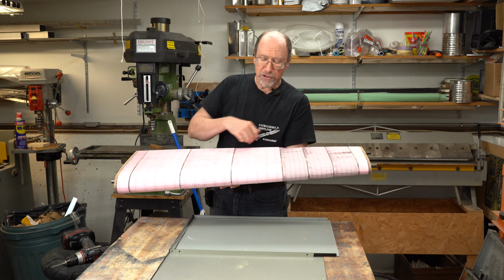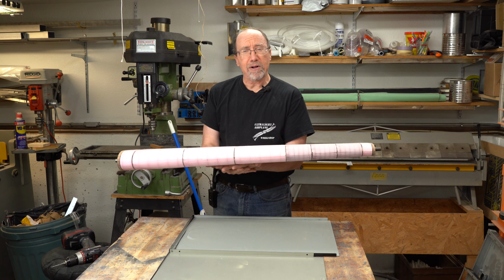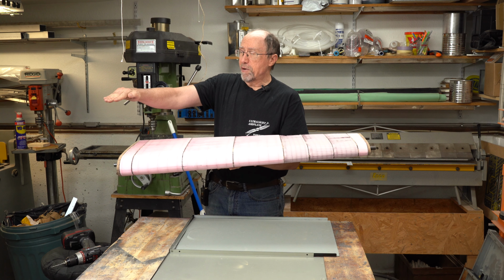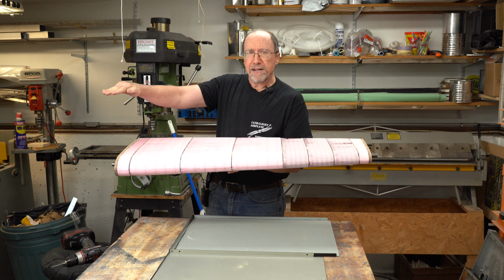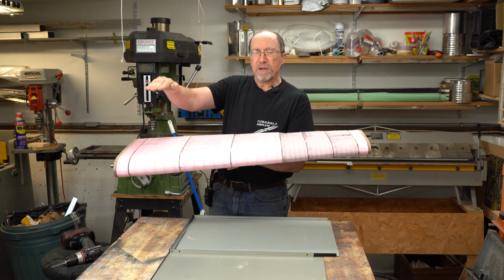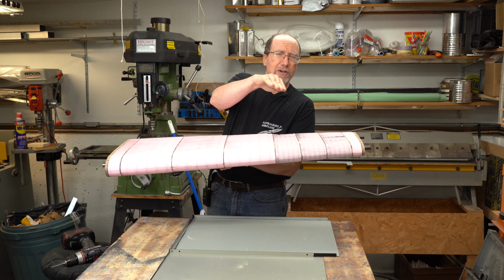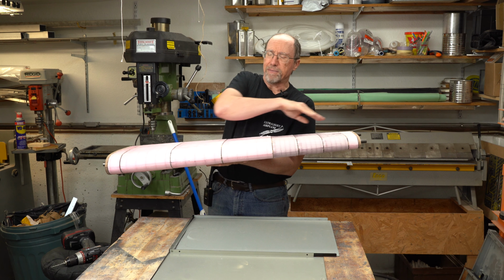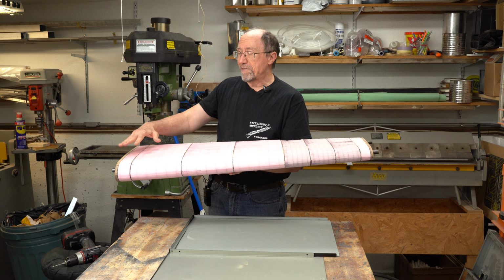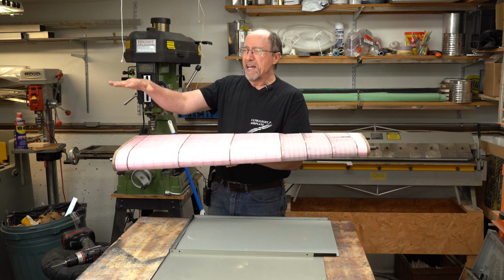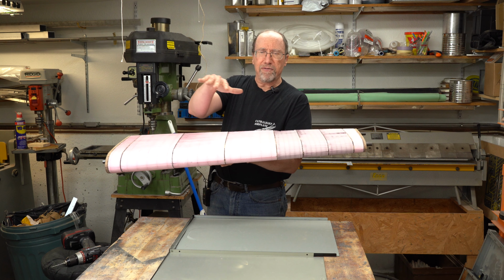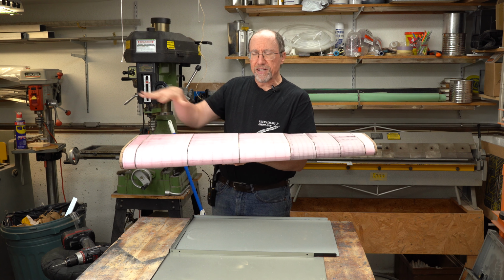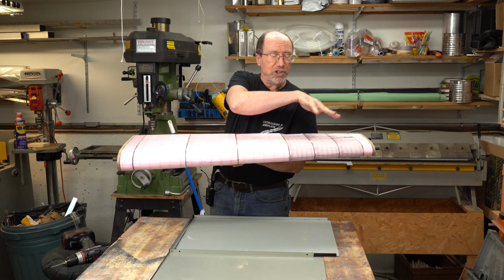On a span load distribution, a large contributor to the shape of that distribution is the planform of your surface. Now, for example, on a rectangular, you're going to have your maximum load out here near the root. It's going to be fairly flat and then start curving off down to zero out the tip. On an elliptical, you're going to have a fairly similar shape, except it's going to be more gradual and fall off the whole way. It won't be a straight line, but more elliptical shaped.